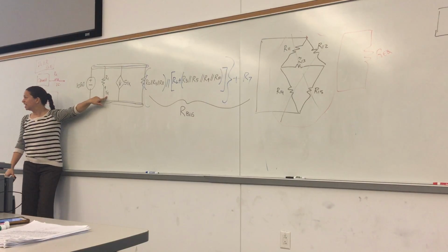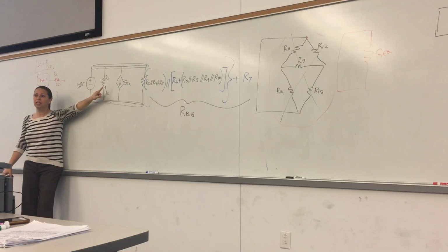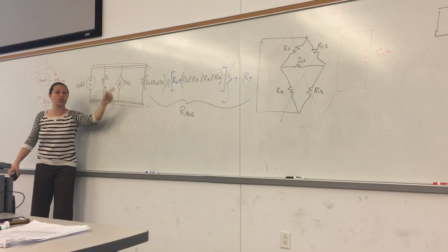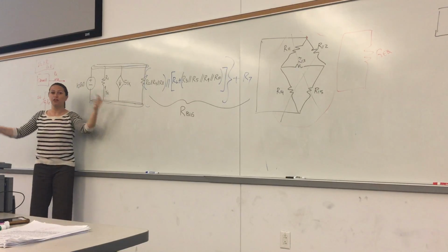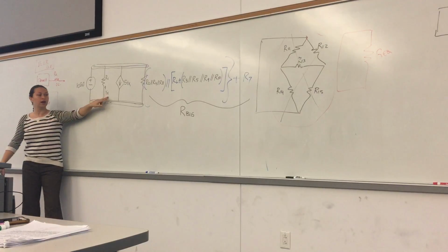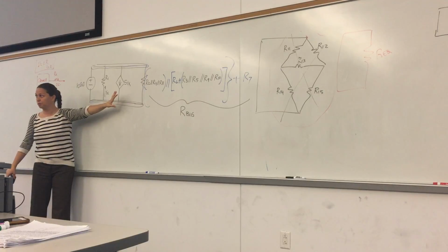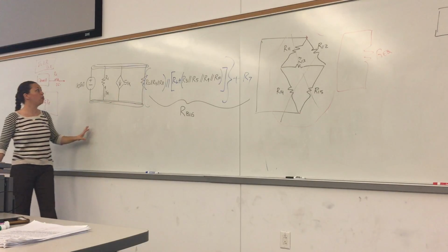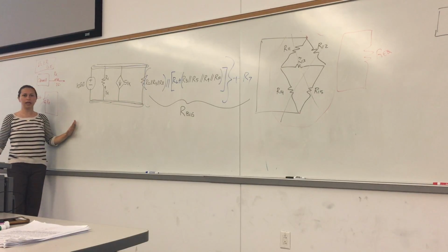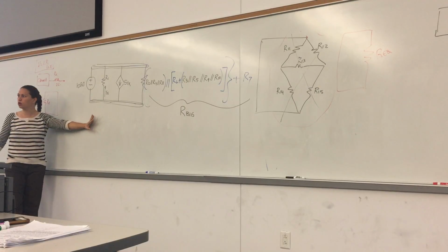IX is the current through R1, not the current through the parallel combination of R1 and R big, right? If I combine the two, IX is gone forever, and then the circuit cannot be solved because of that. Then we're going to be able to find this value, right? So I stop at that point, but that's okay. That's good enough to solve for everything.